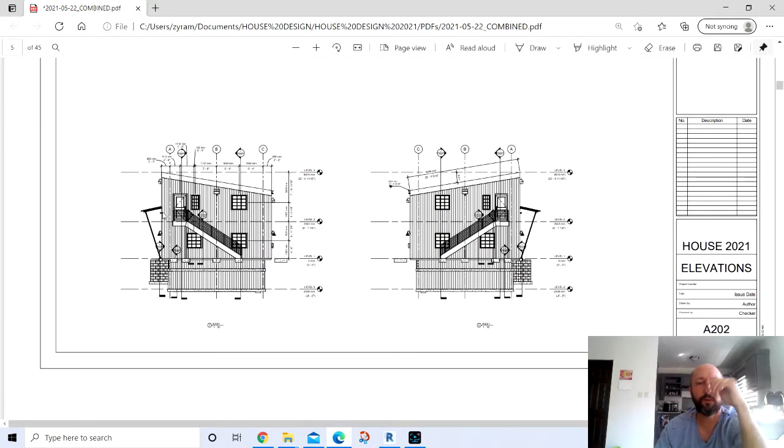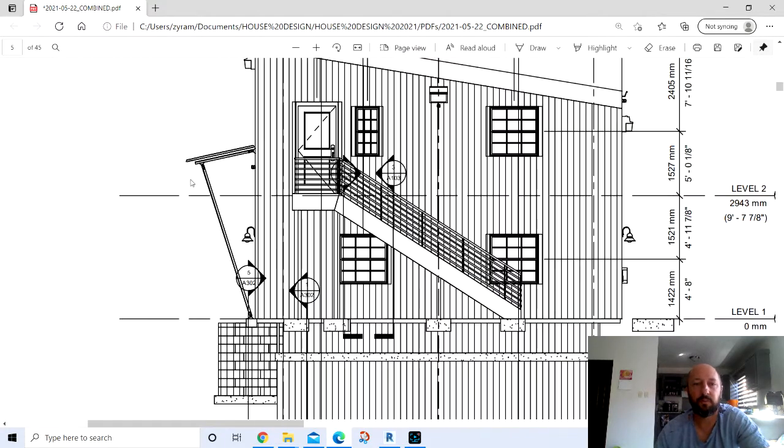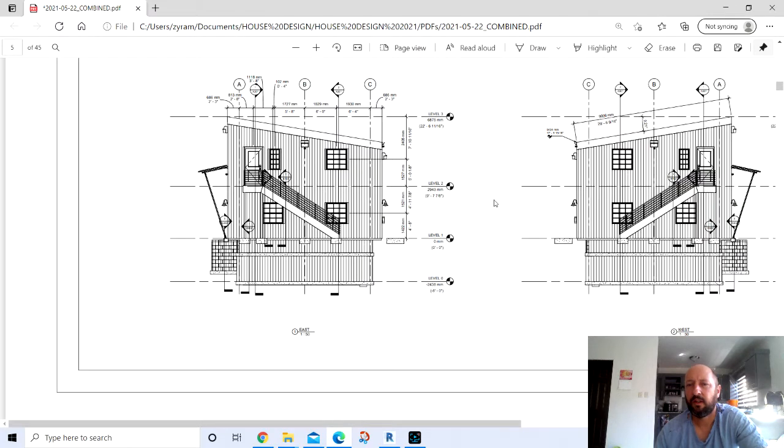And you'll see the solar panels are out front here on the southern side of the house, of course. And the reason for doing that was twofold. One, of course, you want to put the solar panels on the south side of the house to get the sun. Well, at least in the northern hemisphere, you want it on the south side of the house. But also, we'll get to this portion as well, but these braces for the supports are adjustable. So in the summer, you can adjust it up to collect more sun in the summer, and then adjust it down in the winter to collect more sun in the winter.